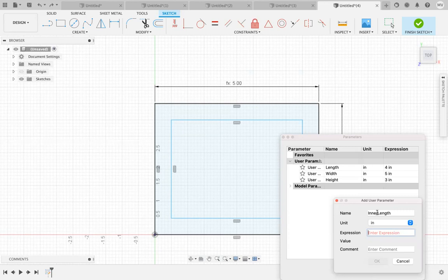I guess I didn't make a parameter for the wall thickness, I probably should. But let's say it's 0.5. I'll add that in right after I do this. If it's 0.5, then this blue line, this vertical one right here, the outer edge is 4. It should be 4 minus a half, and then minus a half here. So really minus 1 inch. So some people are like, all right, so if that's 4, this should be 3.